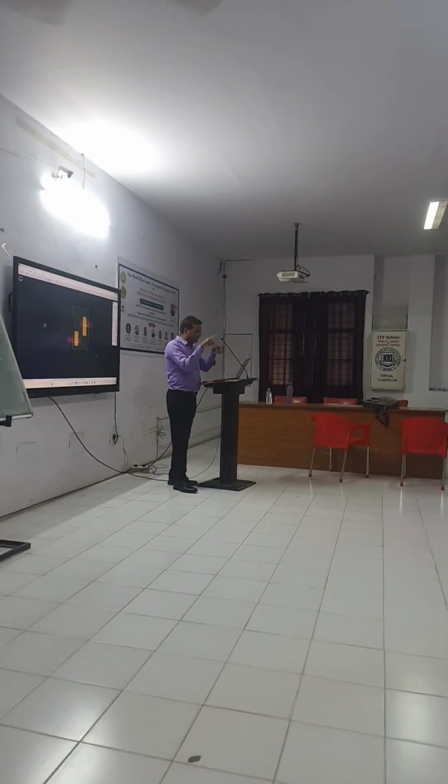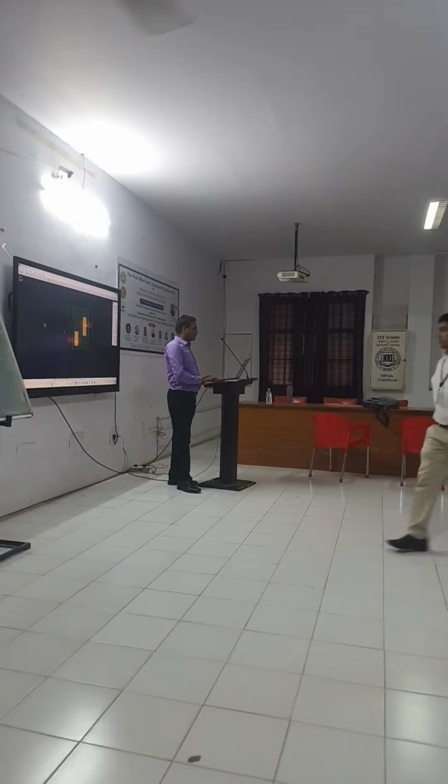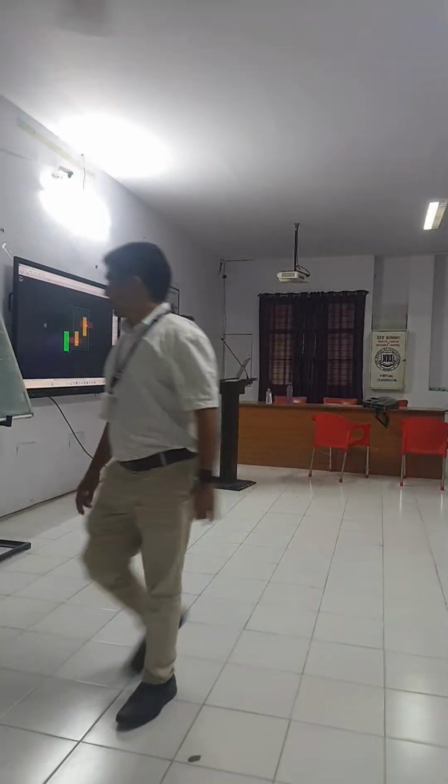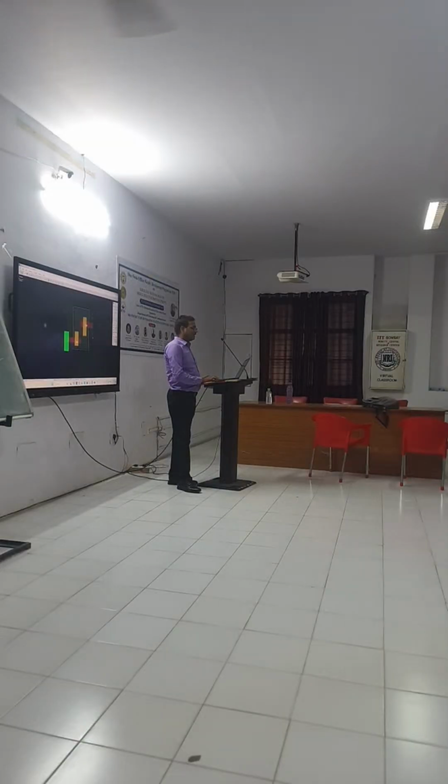So first draw the schematic. Based on the schematic, we design the layout. Getting it? So this is the PMOS. Now we are going to design the NMOS. The NMOS is always outside of the N-well. So here, this is the NMOS. Again, the other NMOS you can see. You get it? This polysilicon should cross.